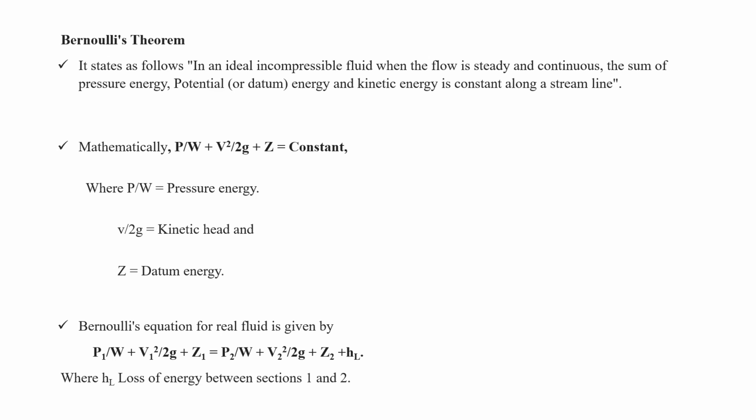Another important theorem is called Bernoulli's theorem. It is also widely known as Bernoulli's equation. It states that in an ideal incompressible fluid, when the flow is steady and continuous, the sum of three energies, the pressure energy, potential energy, also known as datum energy, and kinetic energy, are constant along the streamline.